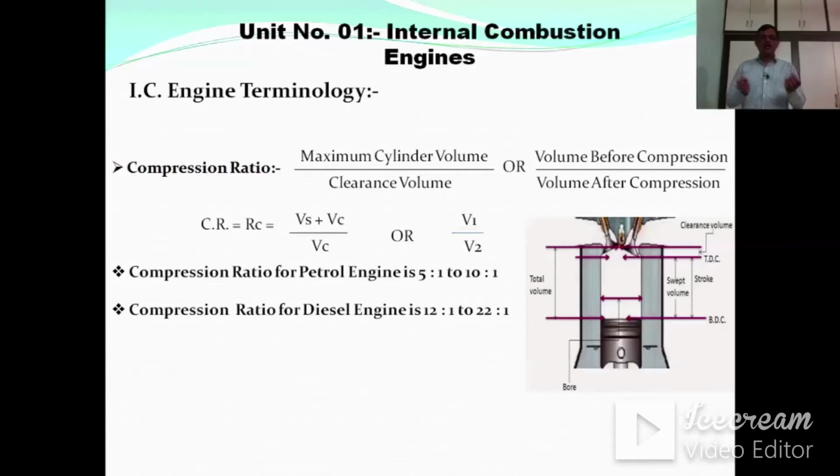But in a diesel engine, only air is compressed. At the end of the compression stroke, the air is fully compressed. At the end of the compression stroke, by the fuel injector we inject the fuel in the form of a spray. This fuel mixes with the compressed air and burns automatically due to the compression. Hence the diesel engine has the higher compression ratio.